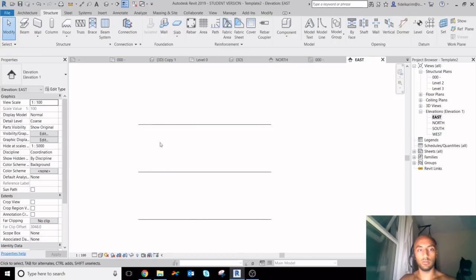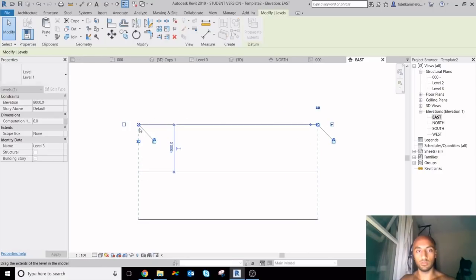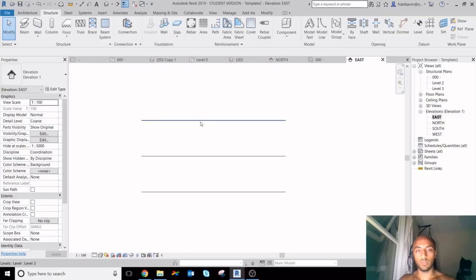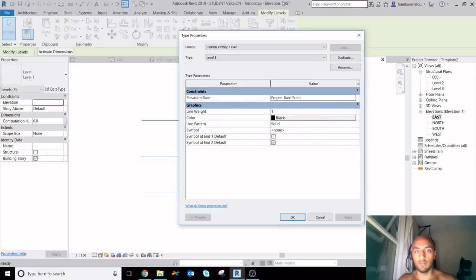Now, the good thing about having them in line like that with these dotted lines is they're associated with each other. So if you stretch one, you stretch them all. The other thing is these don't look very meaty. They're just standard lines. So if you select them all, only the lines, that is, if you've selected something else, you can use filter here to filter those selections out and say edit type.